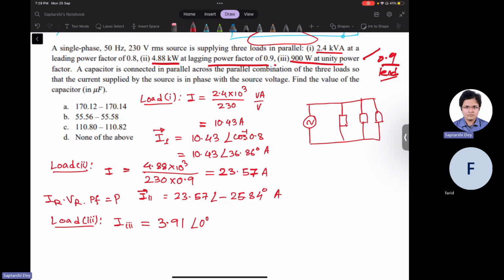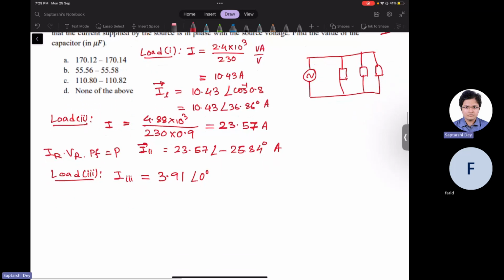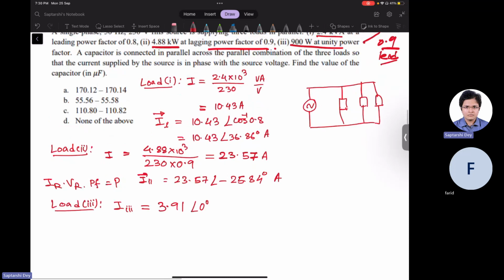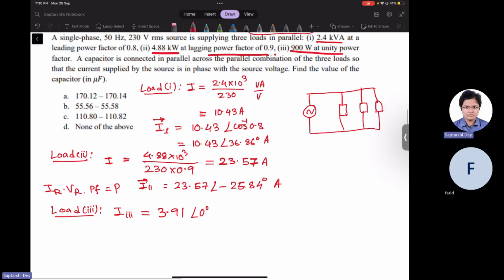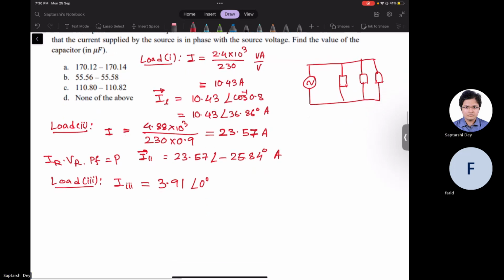Anyone can be taken? No, anyone cannot be taken. Your whole life will pass to complete the phasor diagram drawing. So whenever we are drawing phasor diagram for parallel circuits, our reference phasor will be the voltage of that parallel branch, because voltage is same for all of them.